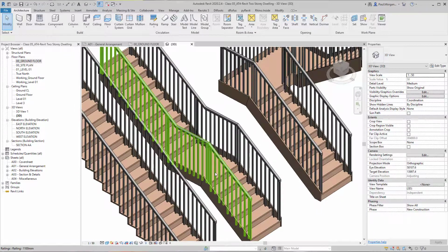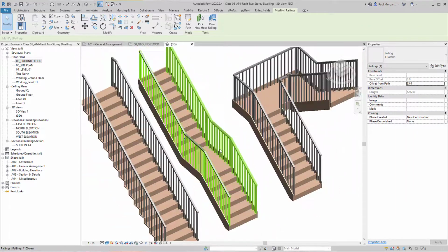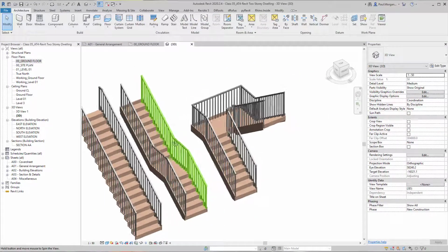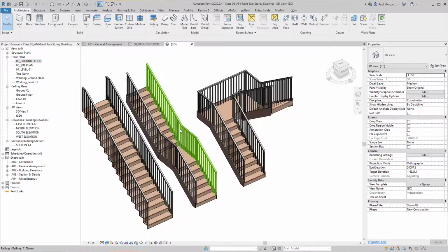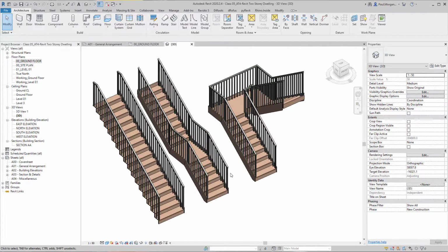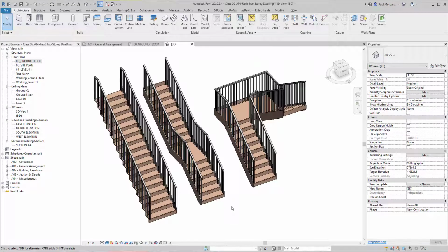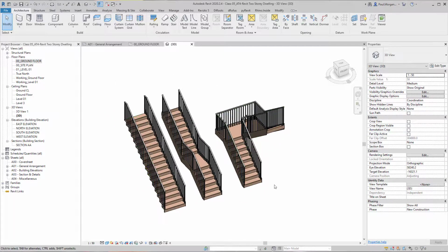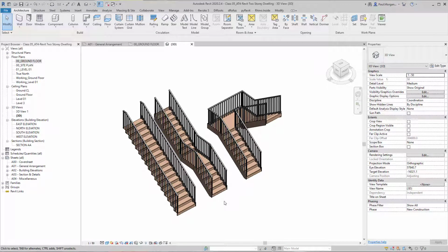Bring everything back, and then you've got handrails. There are a multitude of different types, and I'm going to go through the basics of a basic pipe and how to run with that, because that will be for your commercial stair. But I'll go through that when we go through the commercial stair itself. So that wraps up, I think, stairs as a whole in terms of what is selectable. But again, we haven't touched on handrailing yet. That's just stairs. And so next up, we'll go through how to do a monolithic concrete stair with a typical pipe handrail profile.